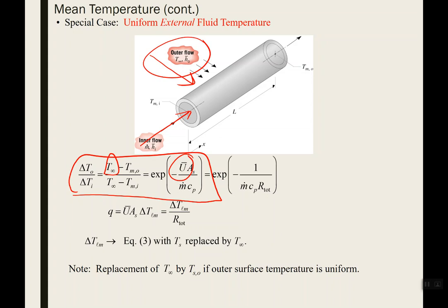So when you're talking about heat exchangers, you'll typically deal in terms of U, the overall heat transfer coefficient. You'll have two fluids. One is going through a pipe, the other one is on the outside of that pipe. So there's convective thermal resistances for each of them, and there's a conductive thermal resistance through the pipe wall. So you're going to have to back solve to get U instead of dealing with the h's. Questions there?